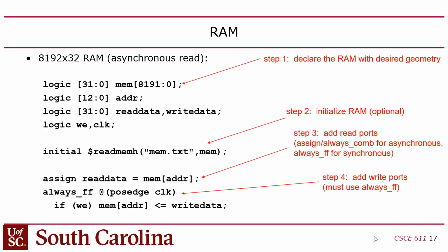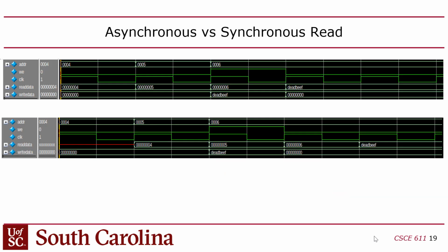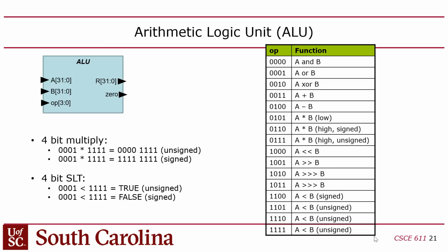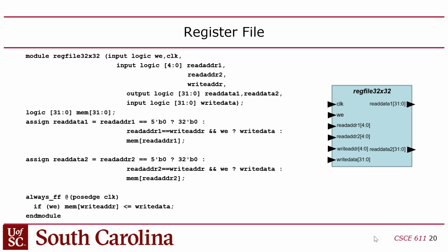Okay, so this is the RAM. I already covered that. Okay, and then I think the last thing I talked about last Monday was the register file. The register file is kind of strange because it's a RAM that has 3 ports. You can do 3 accesses simultaneously, but 2 of those have to be reads and 1 of them has to be a write.